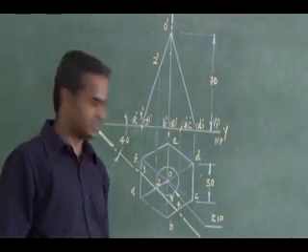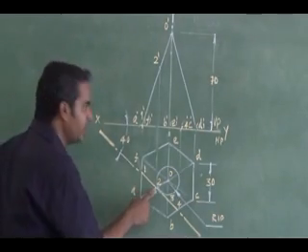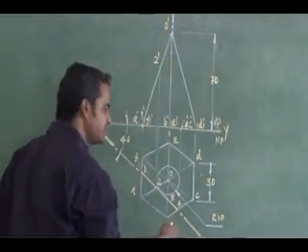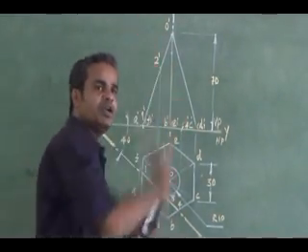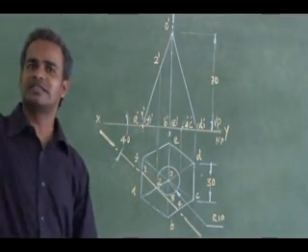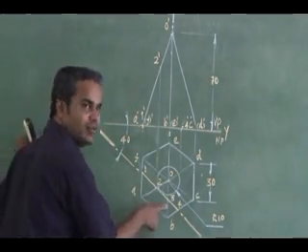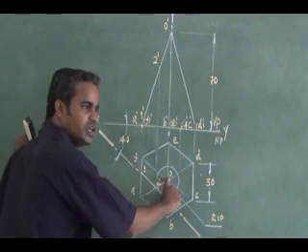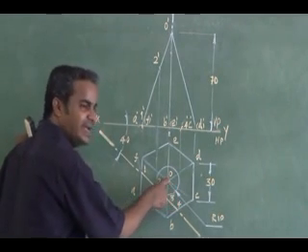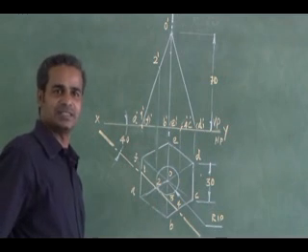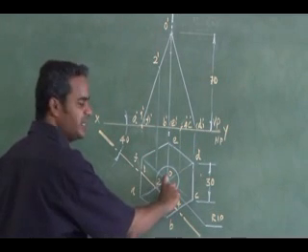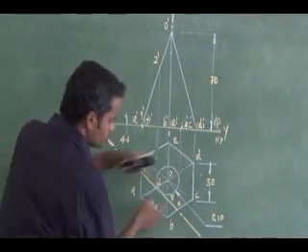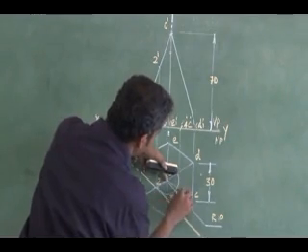There is a process. This cutting point is directly projected to OA since it is a slant edge. Here it is not able to project, since the slant edge in both the front view and top view falls on a single projector. So see here, this distance, O to 3 distance, I will mark it on any other extreme slant edge, say OC. So I mark the O3 distance on OC.